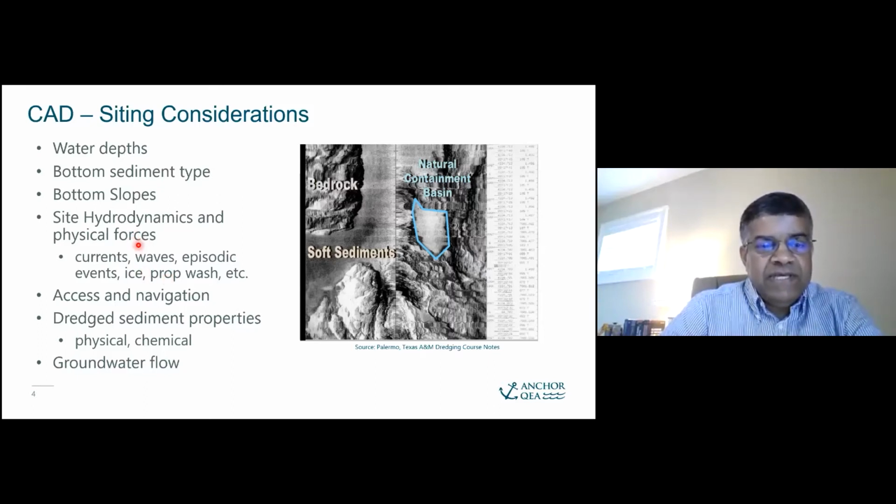And of course, the bottom sediment type and the placed material also plays in very closely with the dredged sediment properties. So this is a fill material, not the excavation that you do to create the CAD. And that's important because of that process of bearing capacity issue that Steve mentioned in Boston Harbor Cell that's been studied quite a bit, and it's fascinating to see that summary from Steve. So essentially the rule is make sure we know enough of not only the in situ material, the material we're placing, as well as how it is placed matters.